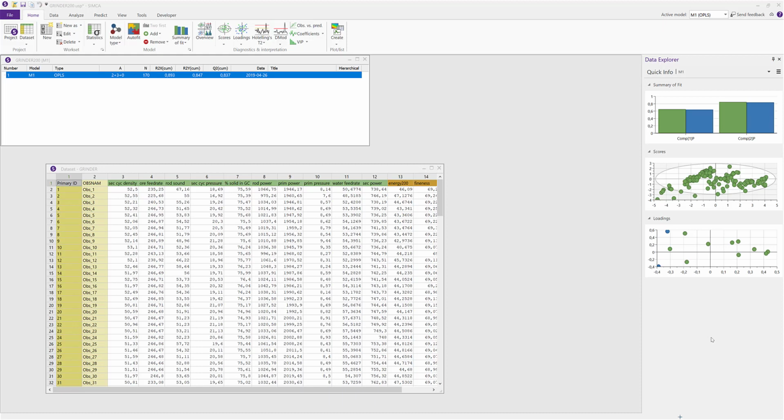Here we have process data from a mineral grinder. Mineral ore comes in and is ground to meet the desired fineness criteria. At the same time, we also keep an eye on the energy consumption per produced unit of the product. So for any given fineness, we want to know what the variable profile looks like that at the same time reduce the energy consumption. First, we fit an OPLS model with energy and fineness as the two Y variables, which are already done here.